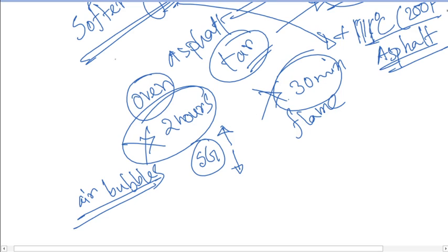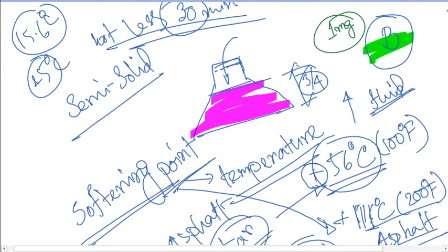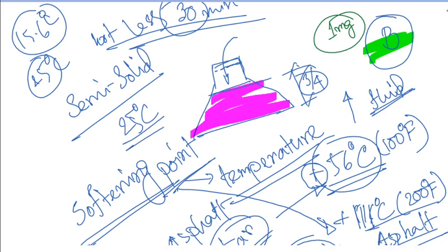However, whenever you have filled up this pycnometer to 3/4 of the volume using the semi-solid bituminous material, then you need to think about what? The temperature of this semi-solid bituminous material is raised to a temperature which is not actually the 25 centigrade temperature as we are expecting. So while pouring this, you need to keep focus that no remaining portion should come in contact with the surfaces.